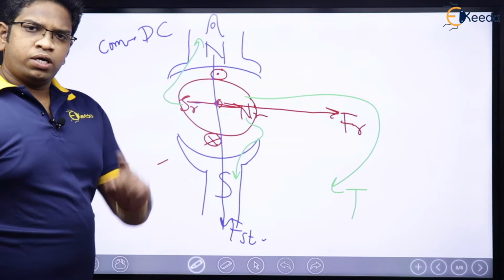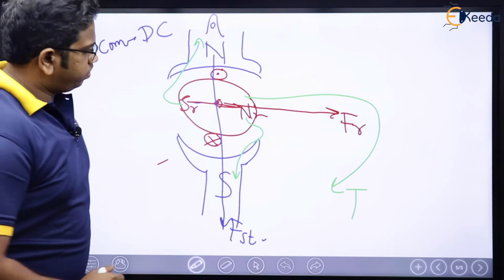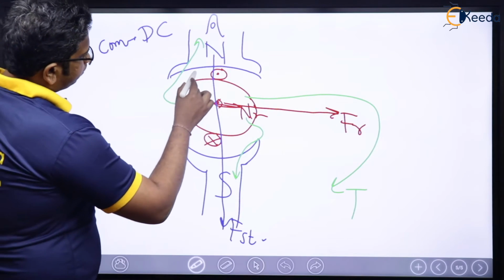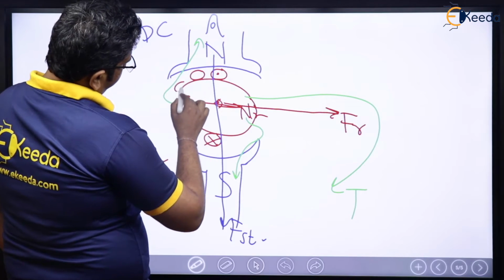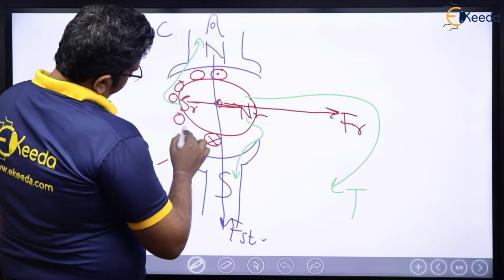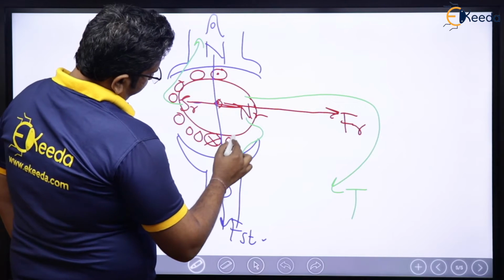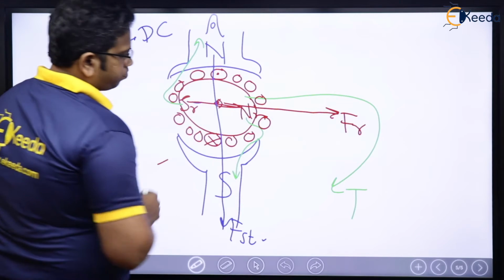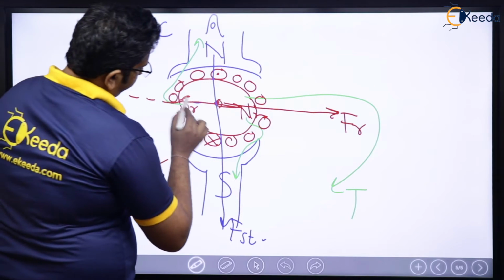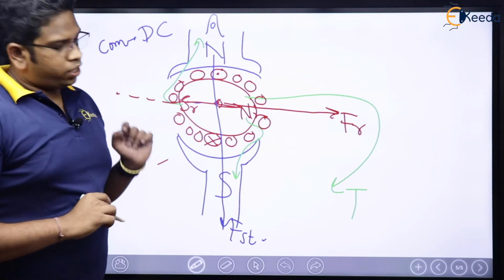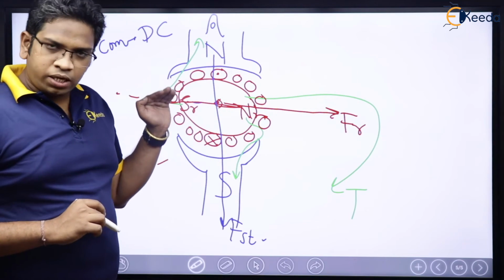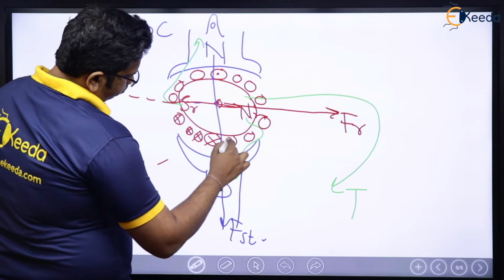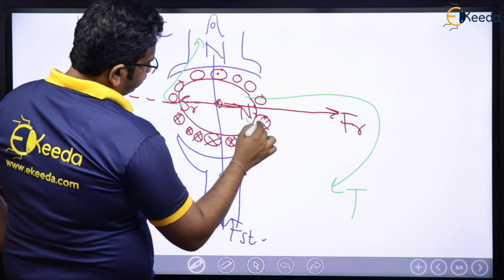Yes. So now, please tell me, in a practical machine, will there be only two conductors? No, there will be many conductors here like this, right? And if I draw an axis here, then in order to have the rotor flux in that particular direction, all these have to be cross, and all these have to be dot.